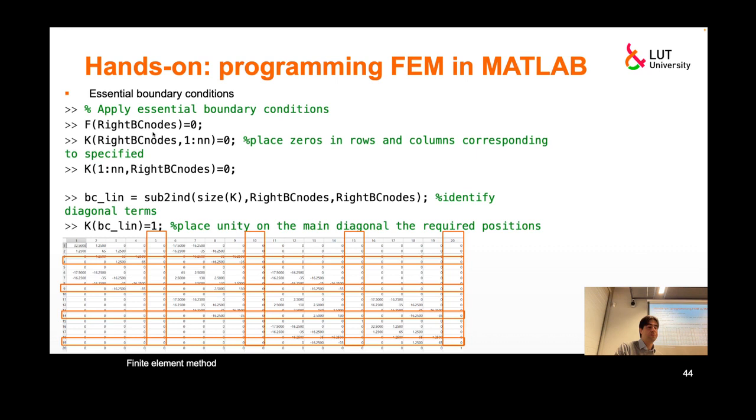So we have this matrix equation Kt equals f, and if we make, for certain nodes, this matrix kind of diagonal, it's 0 in the row and in the column, and 1 at the intersection.